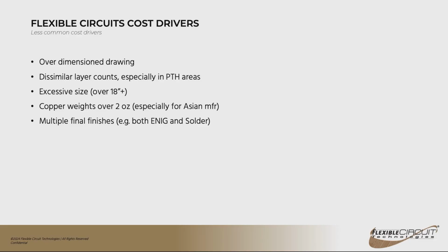There are actually calculators for that. If you have the Polar calculator available, they do have a module in there that covers crosshatch shields so that you can determine how much spacing you need between your signals and your planes to get the impedance that you want.